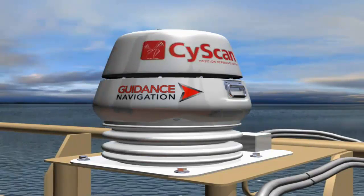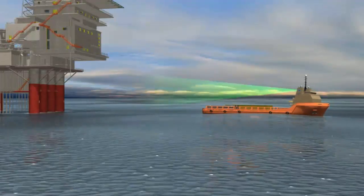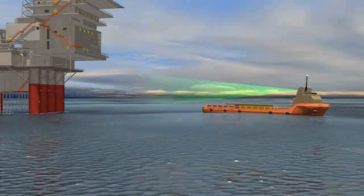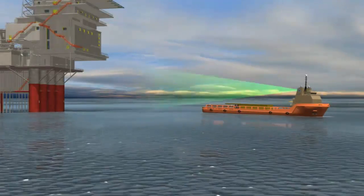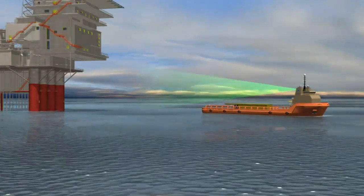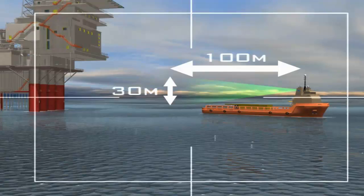Cyscan's sensor head rotates at 1 revolution per second. The laser profile is narrow and deep to allow for wave motion and vessel pitch and roll, whilst maintaining accurate track of the available targets. At 100 meters range, the beam is almost 30 meters deep, but only a few centimeters wide.